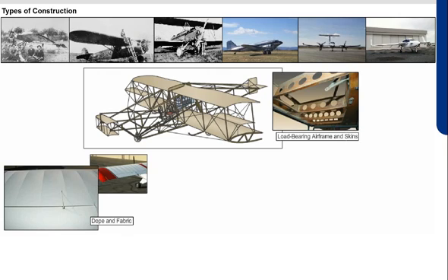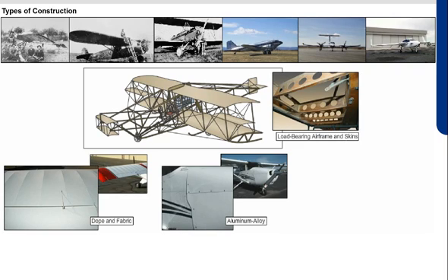Until the late 1950s, fabrics were used for aircraft fuselage, wings, and control surface coverings. The fabric was glued, sewn, or laced to the wood or metal airframe, soaked with water to shrink the skin and remove wrinkles, and then doped to further tighten, seal, and protect it. As manufacturing techniques advanced, thin aluminum alloy sheets were used because they provide a lightweight and reasonably durable structure. Manufacturers can form these sheets into compound curves that enable them to create complex shapes that require little maintenance.